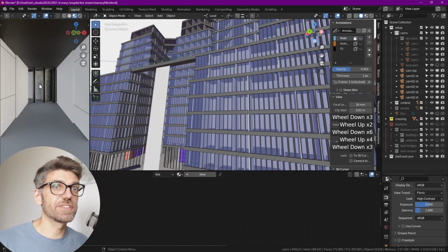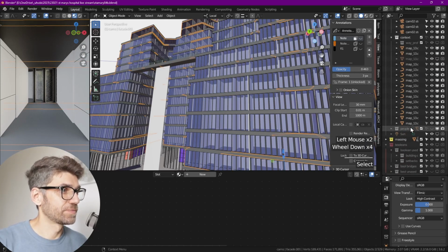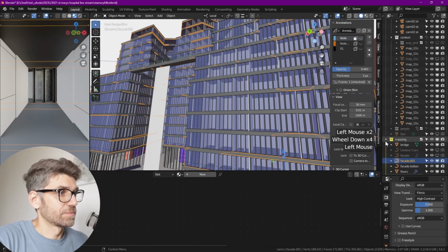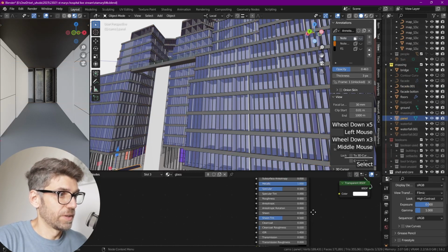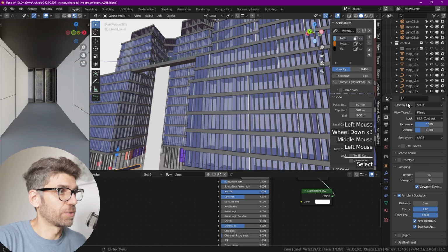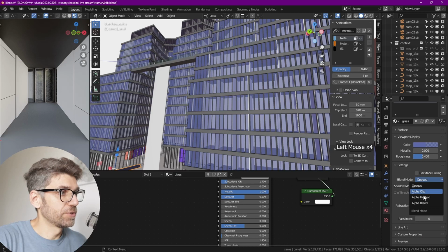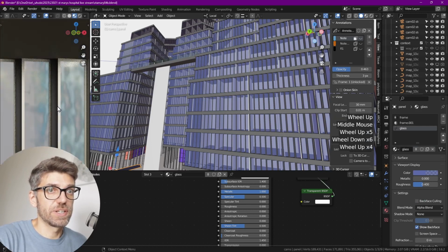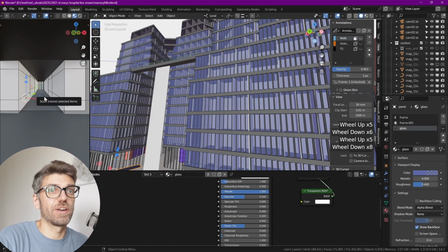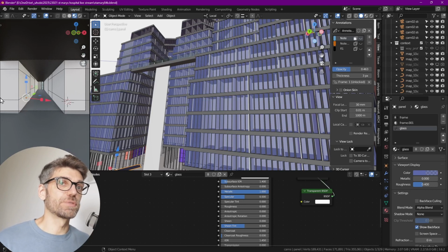So the idea is that from there, let's give that glass material a little bit of transparency. Massing. Panel. Glass, and that's an EV setting only. So once we have EV, if we go to the material and blend mode, alpha blend, shadow mode, none. When we have glass, and now you see that we see through, and we see a little bit of that waterfall in there.